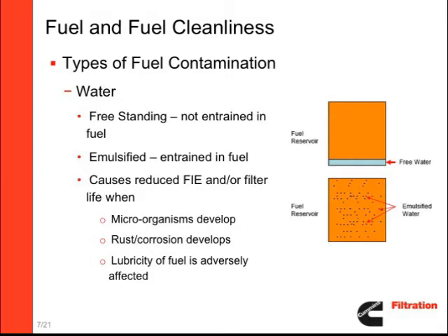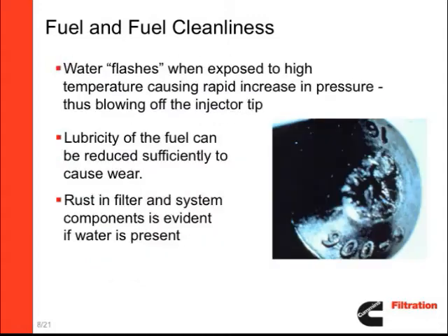Water in the FIE system can cause reduced equipment or filter life when microorganisms develop or when rust or corrosion develop. Also, water adversely affects the lubricity of the fuel, which we'll discuss in a minute. If water enters the FIE system, it can flash when exposed to high temperatures, causing a rapid increase in pressure and possibly blowing the tip off the injector. As you've learned, water affects the lubricity of the fuel. If it is reduced sufficiently, it can cause wear in the equipment. If water is present, rust is evident in the fuel filter and system components.